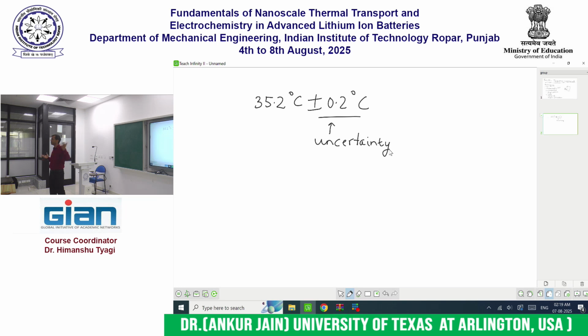Right? Can you think of a scenario where plus or minus 1 degree C is okay? Building ventilation, 1 degree C is quite okay, you know. Whether the temperature of this room is 25 or 24 doesn't matter to me. Right? In fact, most devices measure temperature or report temperature to plus or minus 0.5, I think. Right? And in the US, where we work in the Fahrenheit scale, the accuracy there is 1 degree Fahrenheit. Yes, and half a degree Celsius temperature change is roughly 1 degree F temperature change.